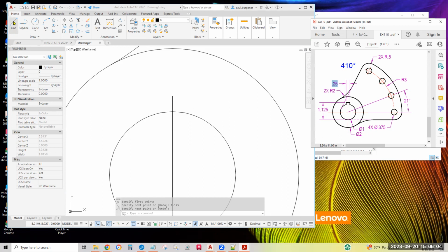Click the line icon. Snap at the end point, go one way or the other, 0.125, enter, and enter again. We haven't learned the mirror command, or I could reflect it straight across or copy it from endpoint there to endpoint there, but that's next week.